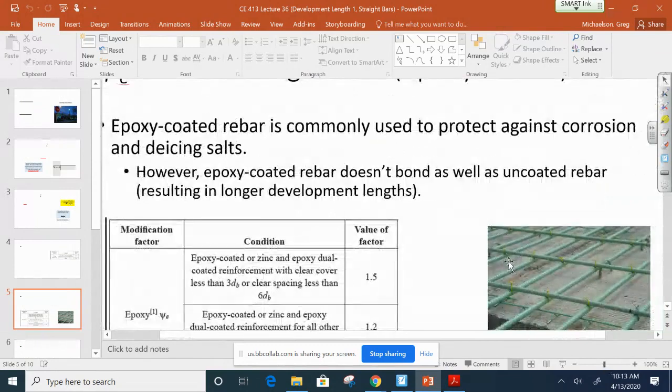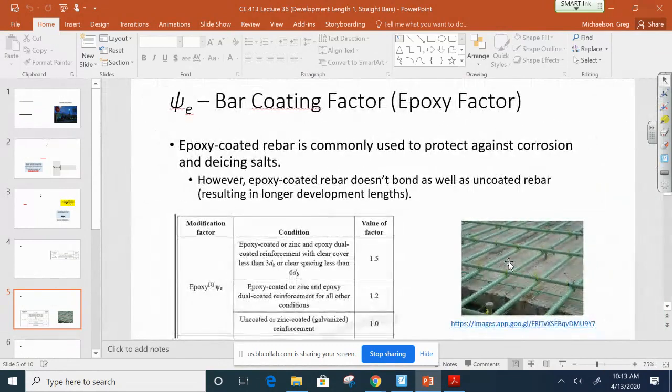And we do that because there's a lot of parameters you've got to consider. Whenever you're casting concrete in the field, one of the things you've got to deal with is corrosion. For instance, we're in West Virginia right now. In West Virginia, if you're talking about a concrete deck, well, what do we put on our concrete bridge decks in the winter?